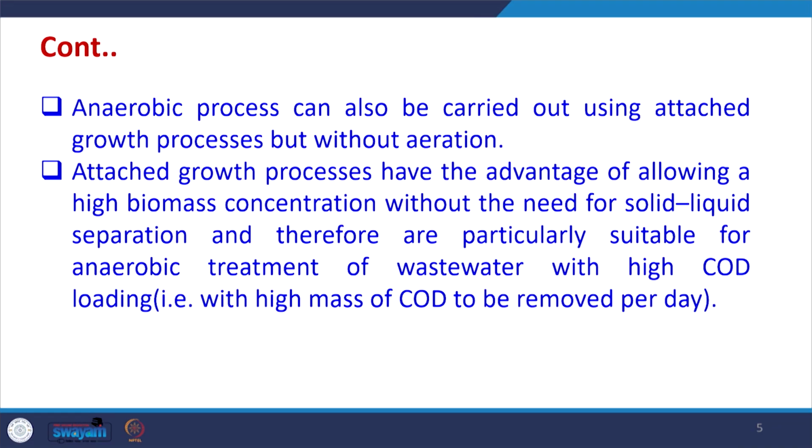So, this is why anaerobic digestion is coming in a big way. Anaerobic processes can also be carried out using attached growth processes, but without aeration. So, it is possible to use attached growth processes without aeration for anaerobic treatment also. Attached growth processes have the advantage of allowing a high biomass concentration without the need for solid-liquid separation, and therefore are particularly suitable for anaerobic treatment.